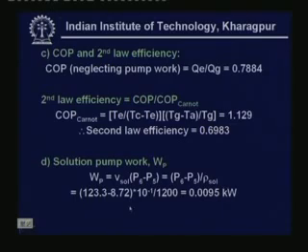So, this is a typical problem on absorption systems. Okay. The procedure is almost the same as for compression systems, but an absorption system is a little more complicated, because you have to deal with solutions and you have to find the properties of the refrigerant as well as the solutions. Okay. For that you need PTX and HTX data. Okay. Once you have the data and once you identify the state points properly, you can easily calculate the required performance parameters. Okay. So, these are two typical problems.